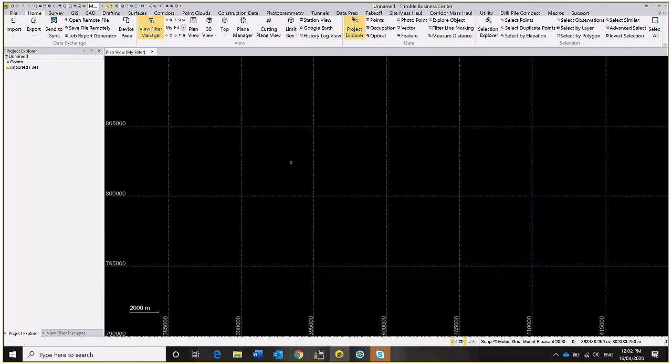Alright, so we can have a look here. If you're ever unsure on what your northings and eastings are, by moving the mouse up and down, you can have a look that you've got your northings on the left there, which is 800,000, and your eastings at the bottom, so 400,000. It just makes it a little bit easier when importing points and data.